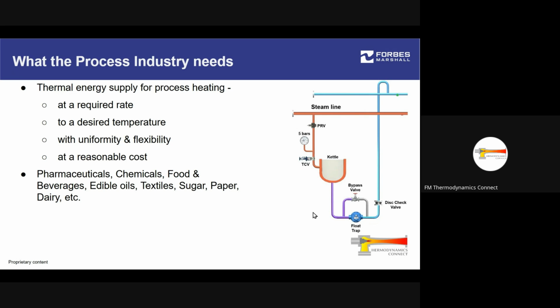Because if we don't evacuate the condensate immediately, it will continue to pile up into this jacket. Now, while condensate will also have some amount of heat, the quantity of heat as well as the rate at which that heat is transferred are both very poor outside the phase change region. So if you have phase change happening, you have high quantity of heat also being transferred at a very high rate of heat exchange.